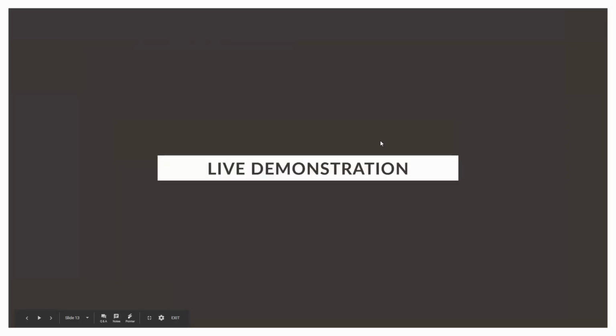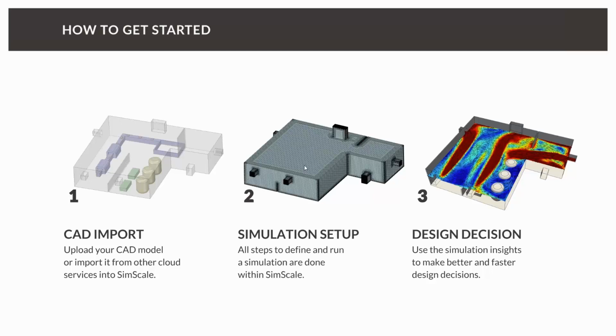And now we are going to set up the simulation, and for this we are going to use the SimScale platform. As a third step, we need a CAD model for our simulation, and you can export it using several tools. We have a lot of customers using Rhino, and you can directly upload native Rhino files. But we also offer different exchange file formats like SAT, IGES, STL, or other native formats, such as Autodesk or SolidWorks. First of all, you need to upload your CAD model, and sometimes it is necessary to prepare the model, like making sure it's watertight or adding the inlet and outlet.